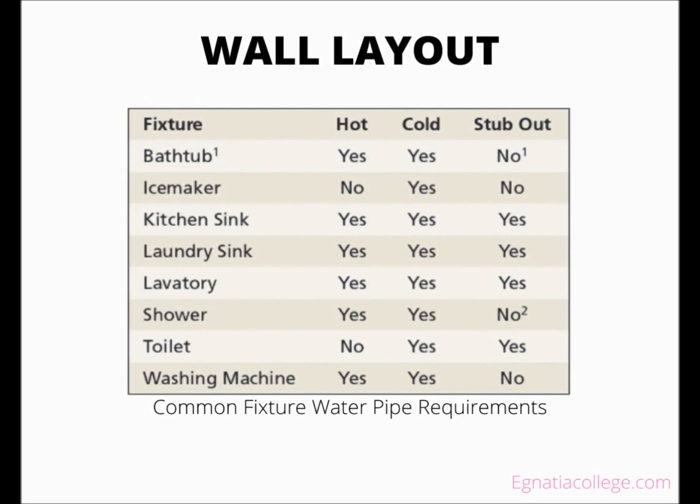There are standard dimensions for typical fixtures, but company preferences vary. A plumber makes sure that the piping that stubs out a wall accommodates the fixture being served. A sink installed in a countertop offers more flexibility as to where a pipe terminates than does a stub-out serving an exposed fixture connection.